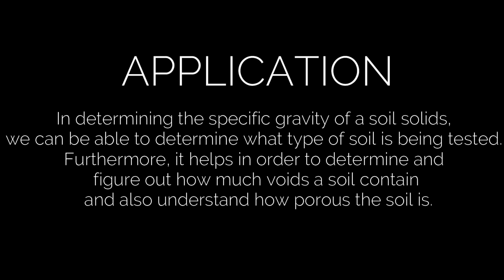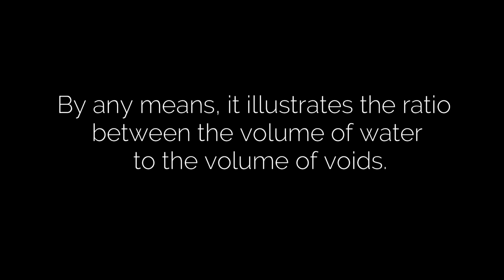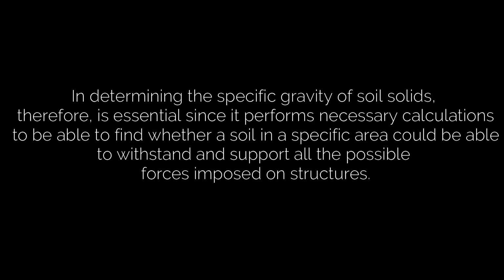In determining the specific gravity of soil solids, we can determine what type of soil is being tested. Furthermore, it helps us figure out how many voids a soil contains and understand how porous the soil is. It illustrates the ratio between the volume of the water and the volume of the voids. Determining the specific gravity of soil solids is therefore essential, since it supports the calculations needed to find out whether a soil in a specific area can withstand and support all the possible forces imposed on structures.